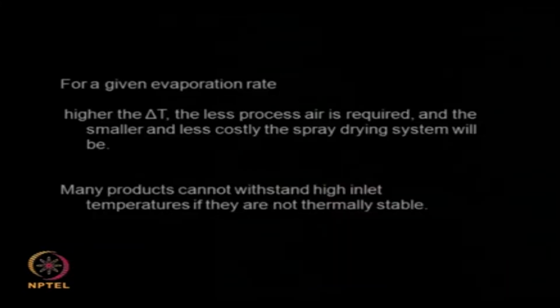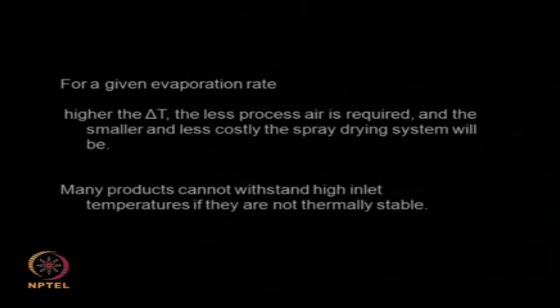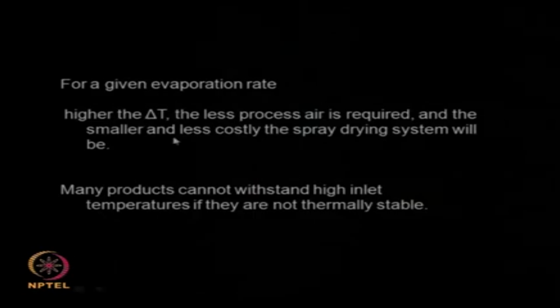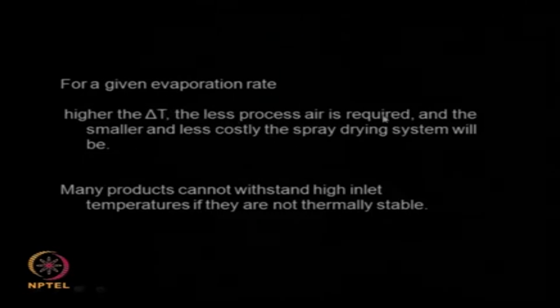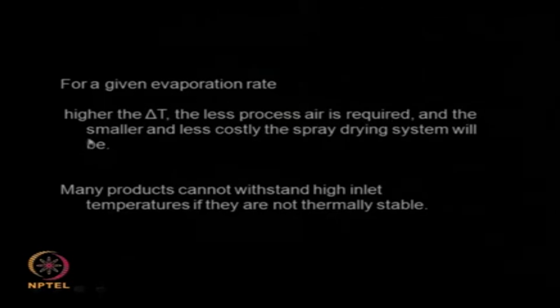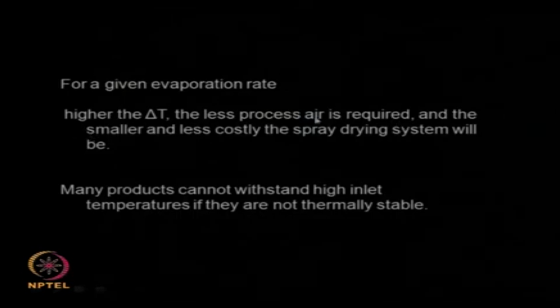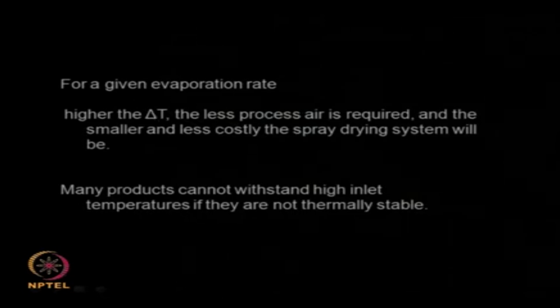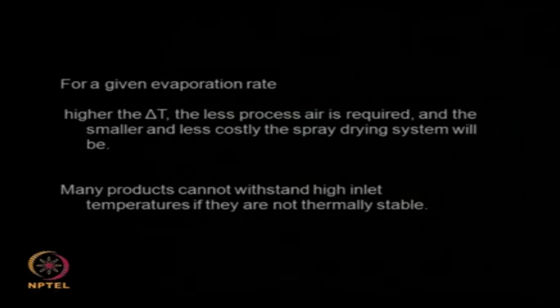So for a given evaporation rate, if I fix my evaporation rate, saying that I want to evaporate so many grams of water per minute, and if I have a very high temperature difference, then I will require less air. If I require less air, then my blower can be smaller, so the whole system can be smaller, so cost comes down, okay. But then the point is I need to have a high temperature driving force, that means the air has to be heated up to a very high temperature.